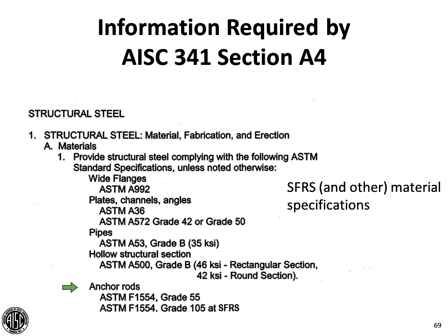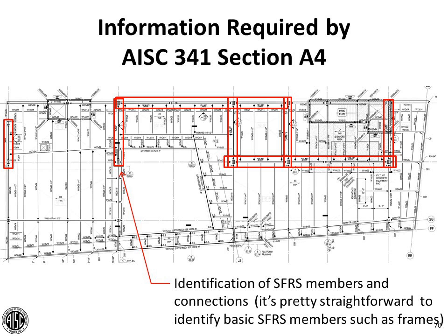And we try to be very careful about where we specify those because it is difficult, in fact it's not possible, to weld them. And so if one of the anchor rods is placed in the wrong position, it can be very difficult to correct that problem. And so we try to limit where we specify the grade 105s.